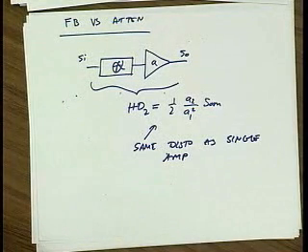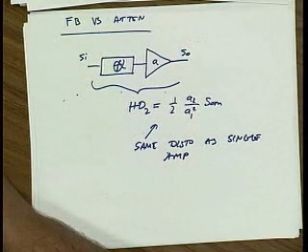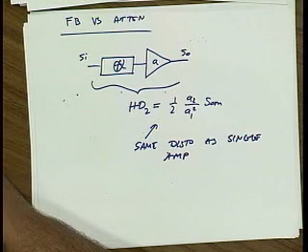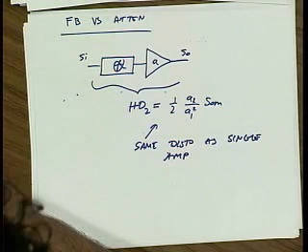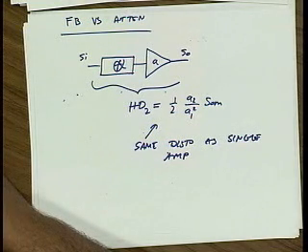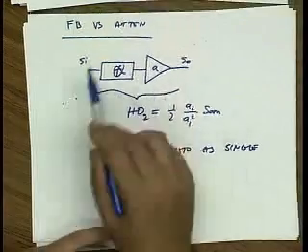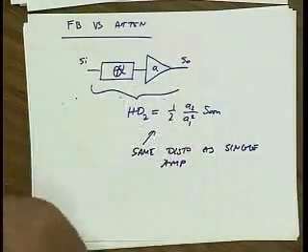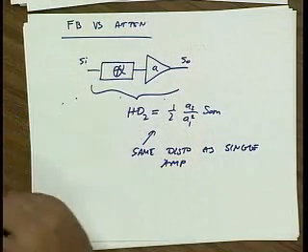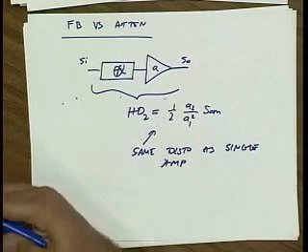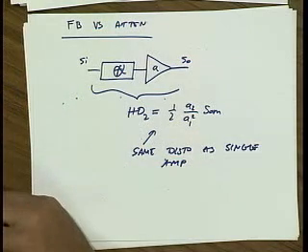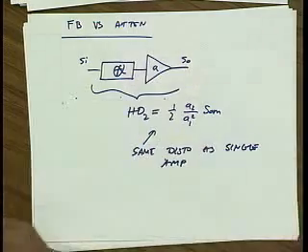Questions or comments? Even if this were to give you the same advantages as the feedback system, in reality these systems are not perfect, and they have all these problems. Feedback is one thing to correct. That's a very good point. Just to repeat your point, even if this did have advantages, you still wouldn't want to use it over feedback, because the whole reason why we use feedback is not just because it improves distortion, but also because it makes our gain insensitive to process and temperature. So feedback has other benefits as well.